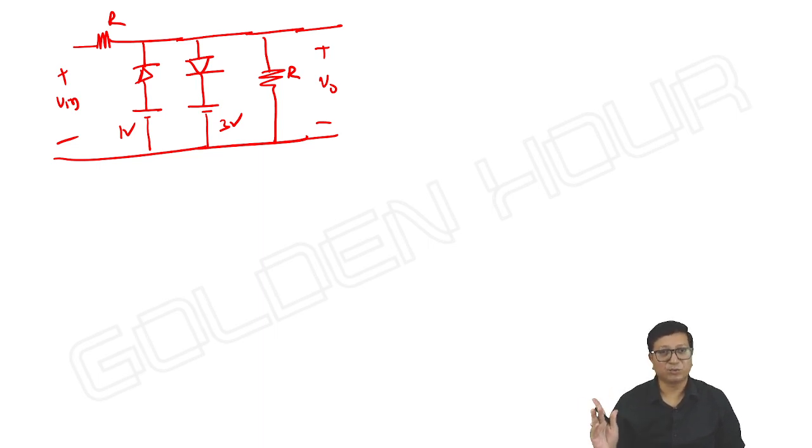Breakpoint 1 is 2 volts and I took a value just below 2 volts, greater than 1 volt. The diode D1 is still on, we have observed it. Done. Next, breakpoint 1 is 2 and between 2 and 3 what happens? Absolutely both D1 and D2 are off.